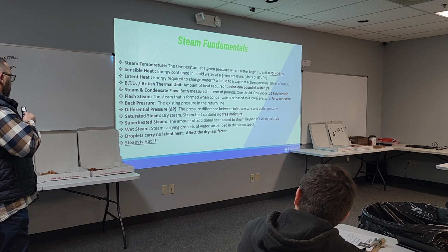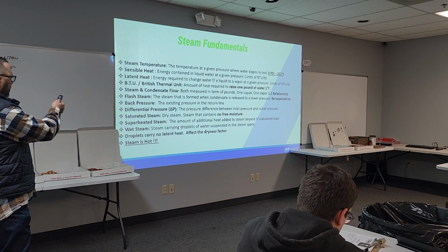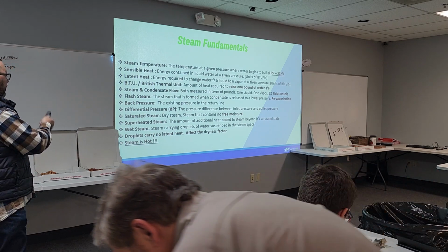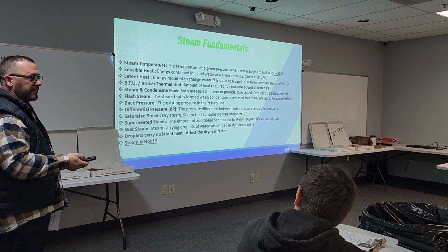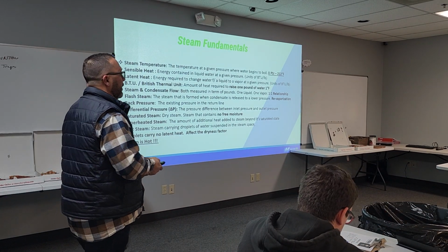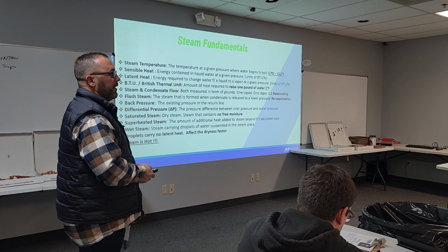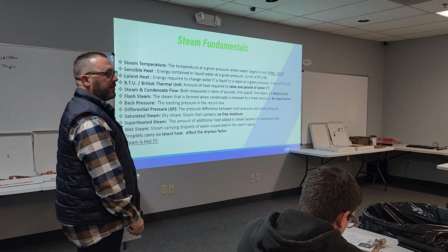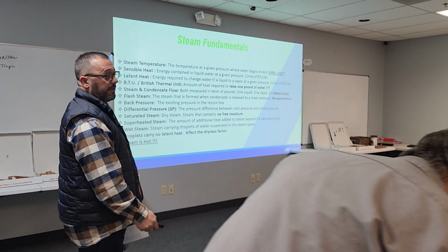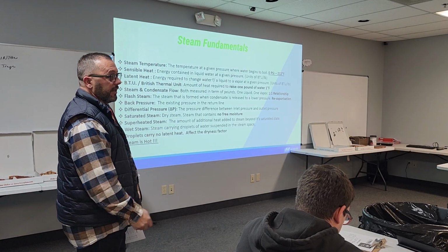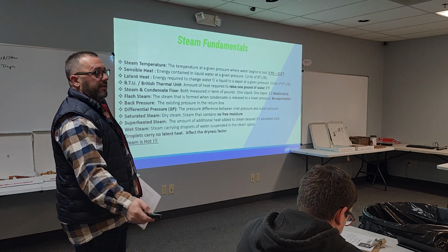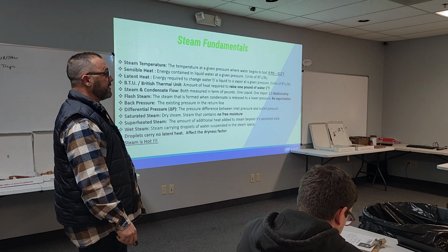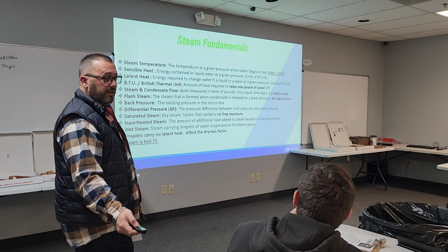Wet steam, again, affects the dryness fraction. It carries no latent heat, and it definitely affects the quality of steam. When we talk about quality of steam, if we say you've got 90% quality of steam, we're talking about 90 parts steam, 10 parts water. It's that simple. You've got 80%? What is it? Nobody really knows. I can tell you that there are manufacturers that have come out with steam quality meters in the last several years.